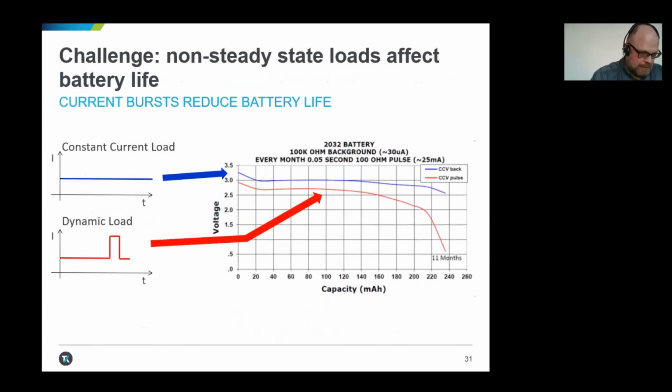You can source your product with a simulated battery discharge curve based on the average current draw for your product. You can discharge the battery down to the shutoff voltage you have established, and you can cycle your product through a usage profile. The discharge time will be based on the most realistic conditions that you can establish.